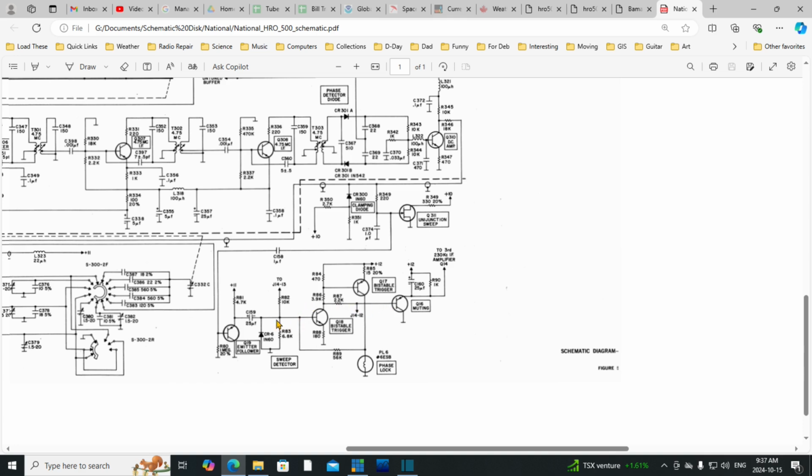And then again, there's another spot over here, on the J14 connector, in position 13, where there's another opportunity to make tests. In fact, they're inviting you to use this as a place to mute the radio. You can stick 12 volts on here and the radio's muted. Or is it 12 volts on here and the radio's muted? I can't remember now. I think it's this one.